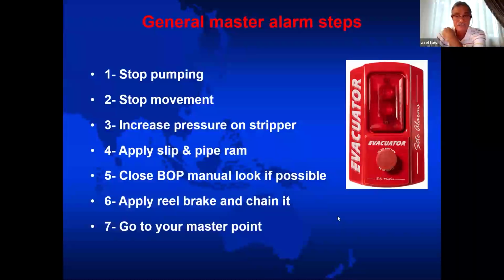I have another question, sir. If there is a deformation on the pipe after it has been used for intervention, will the whole pipe be discarded for a new one? No. Look, if you're talking about the pipe after the first run became oval, that we have to change it, no. You can live with an ovality as long as it is within a certain range. If the ovality exceeds that range, yes, throw the pipe away. But if it is within the limits, you don't have to.